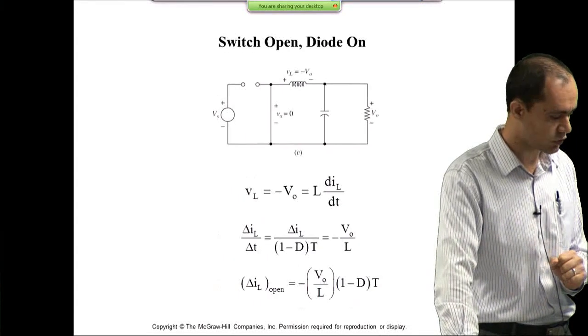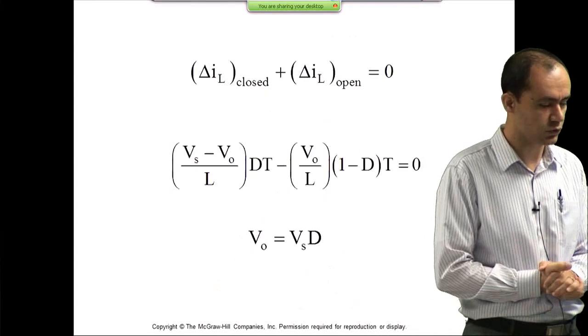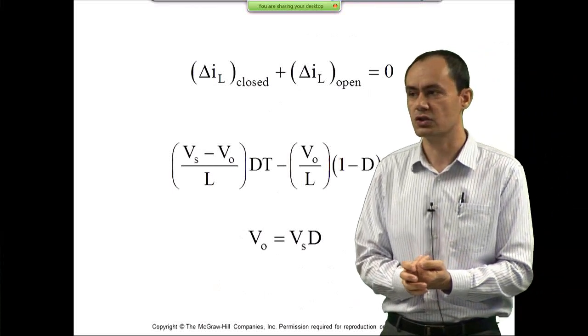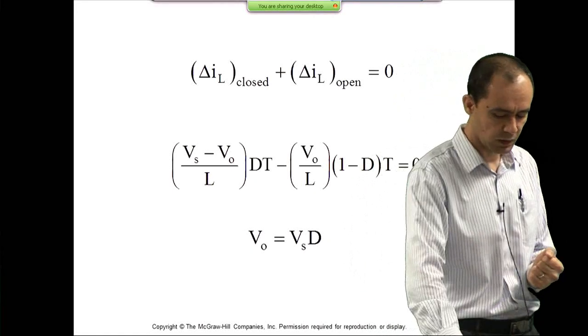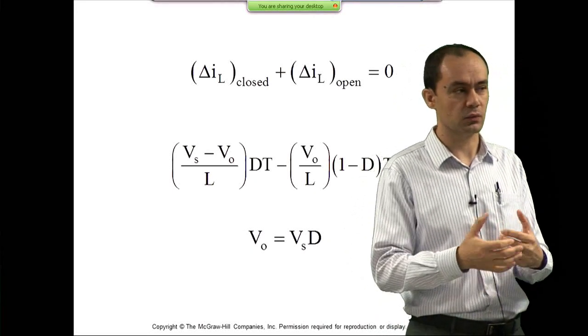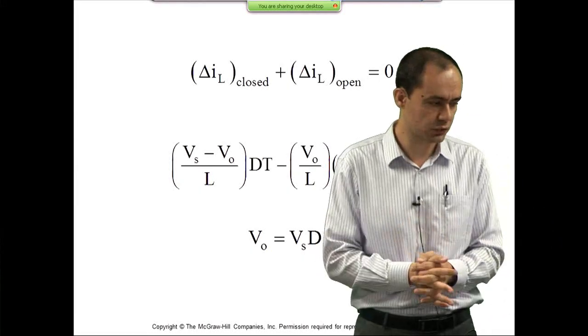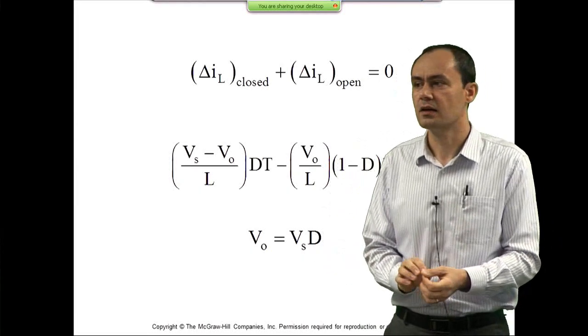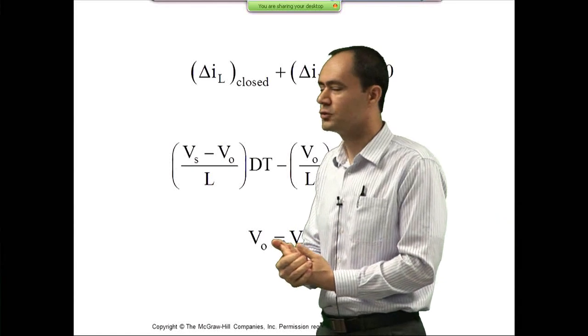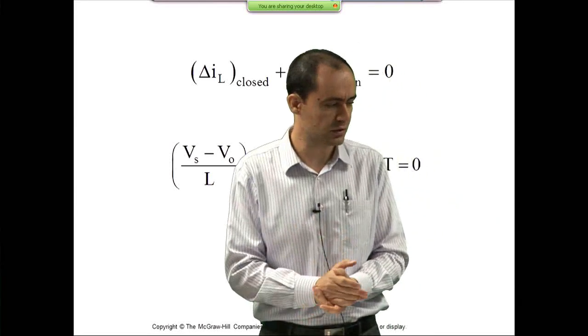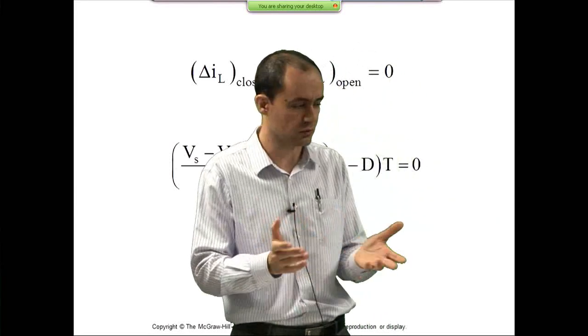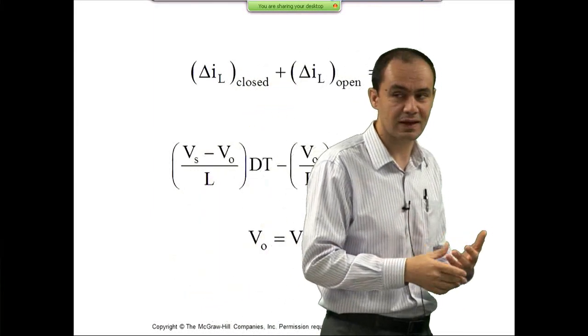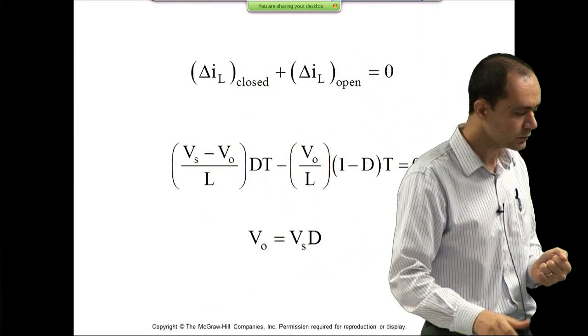We found the voltage transfer ratio of this converter to be Vout over Vin is just the duty cycle. And duty cycle is a parameter that we or the controller can control, in the sense that we can adjust the value of the duty cycle to be 60% or 70% or 50%. It is adjustable. So we can technically adjust the value of the output voltage.